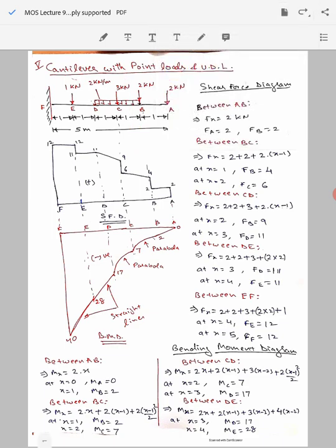Here we are talking about the distance of this load from the cut section, as the distance from the free end of this beam is x. So the load is acting at x minus 1 distance from this cut section. Therefore you get a value of 2 into x minus 1 in this equation, because of the point load acting here.